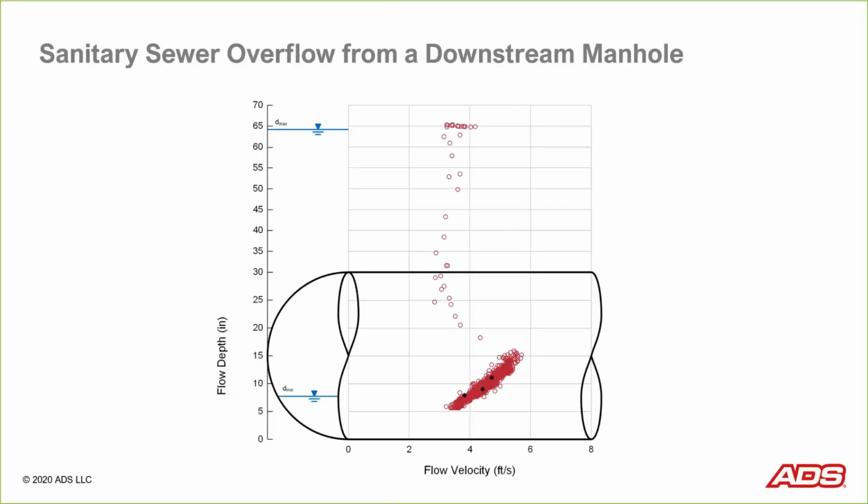So here's an example of a 30-inch sewer. This one comes from California. And again, you can probably already pick out three hydraulic regimes of uniform flow, backwater, and surcharge that are the prelude to an SSO. The Manning equation helps us figure that out, and we can mark those on this scattergraph.